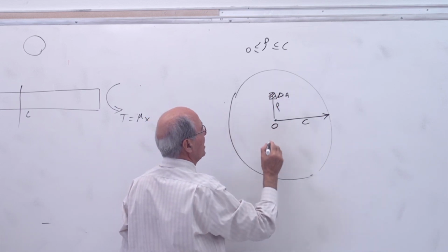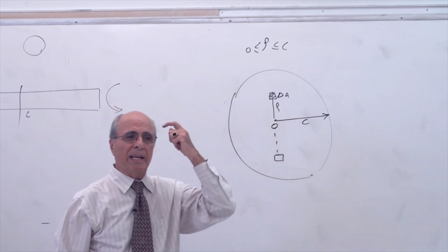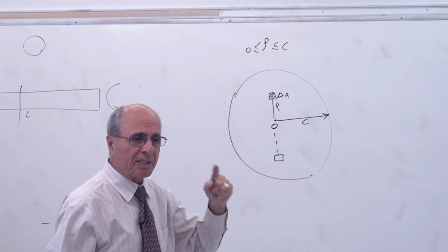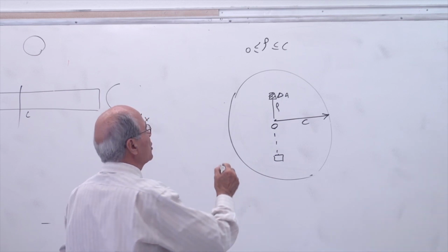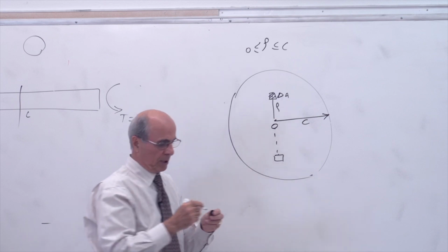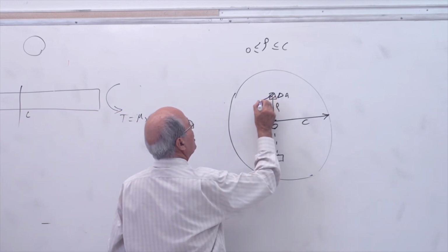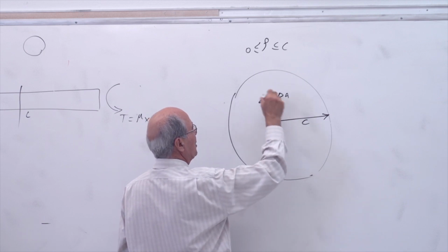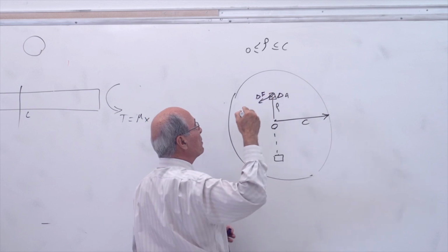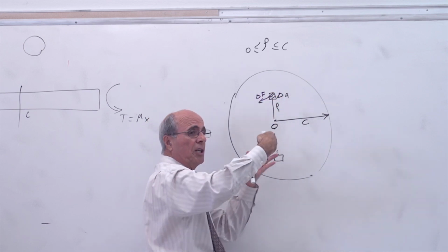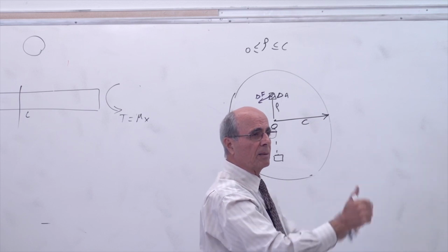So if I have a dA here, similarly, I must have a dA there, which has the forces in it. Remember, those rubbing forces are in the section, yes? So let's call that one a force here. This is the one that gives me the stress. So it's going to be tangent to this circle here. So this is dF. It's not perpendicular to the section. It is parallel to the section because of that rubbing action. Everybody see what I'm talking about?